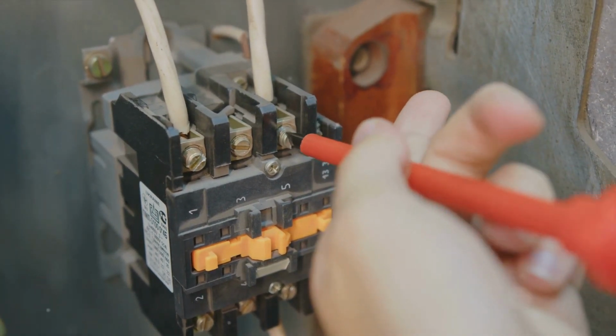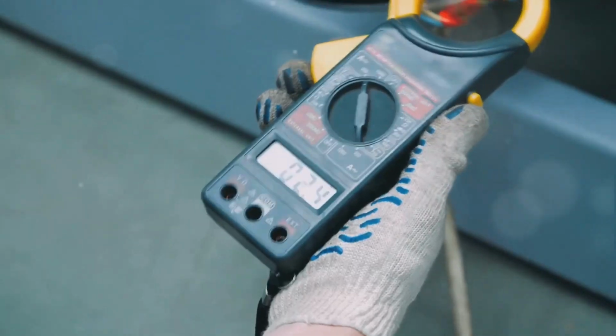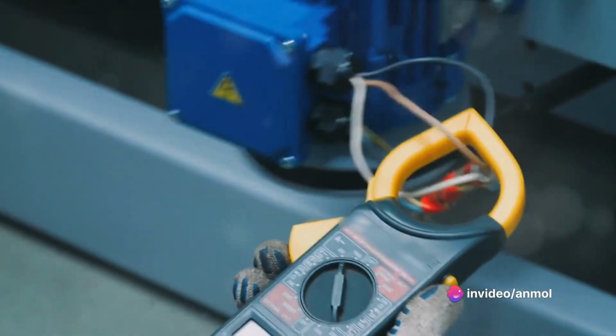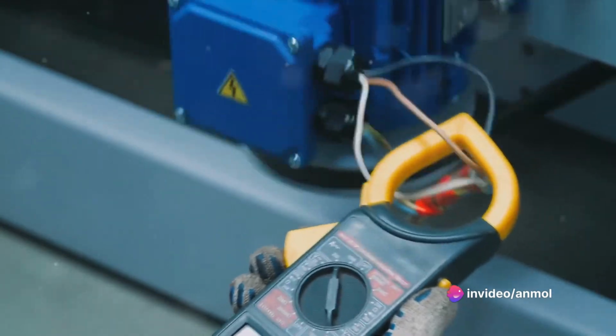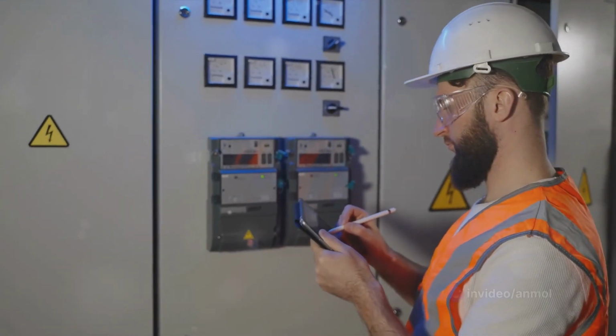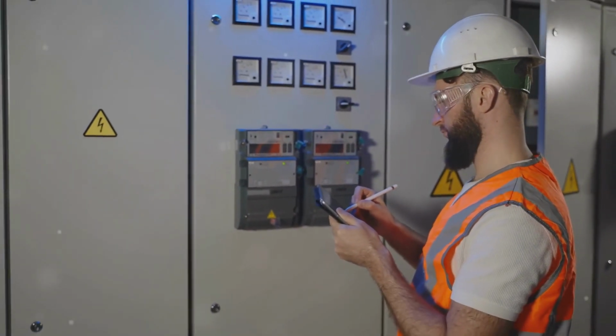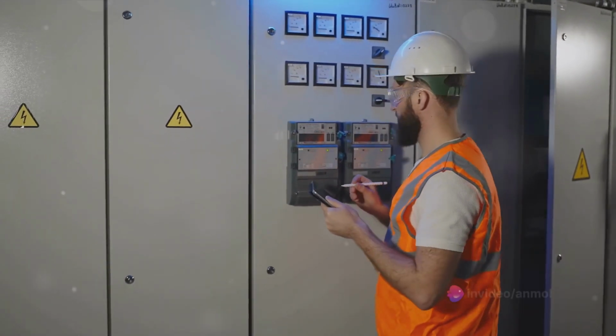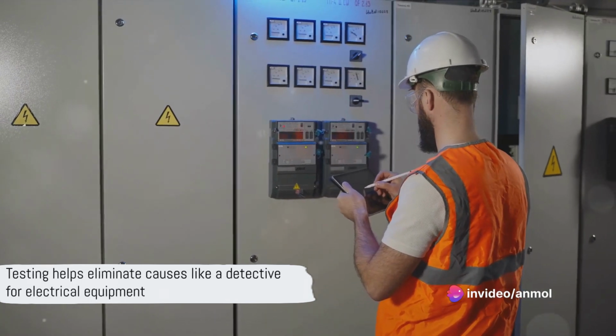This is where the rubber meets the road, or in our case, where the electricity meets the motor. Again, we'll use the multimeter to measure the voltage and current supplied to the motor. If these are not within the manufacturer's recommended range, it could mean the motor isn't getting enough power, or maybe too much. Remember, testing is a process of elimination.